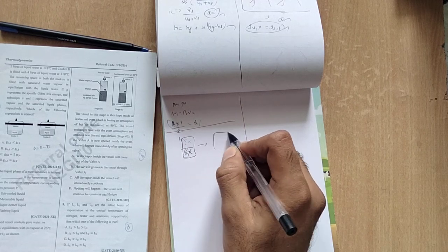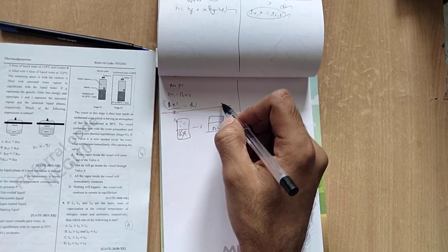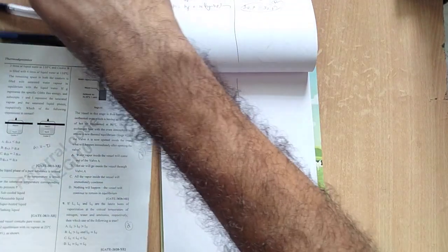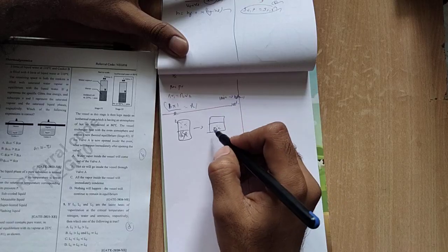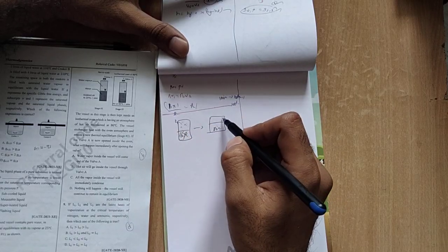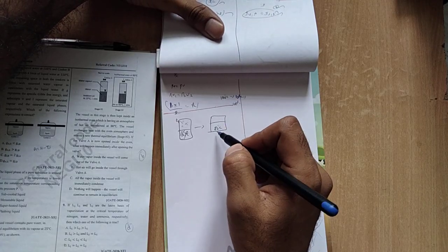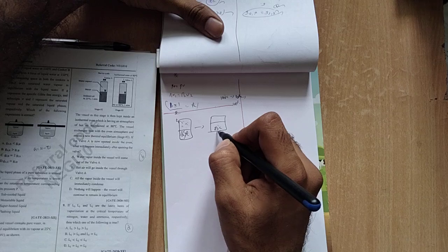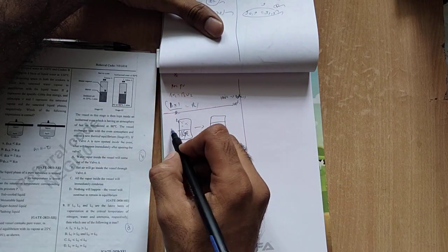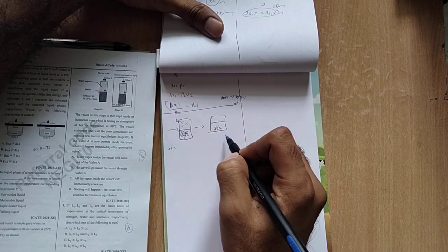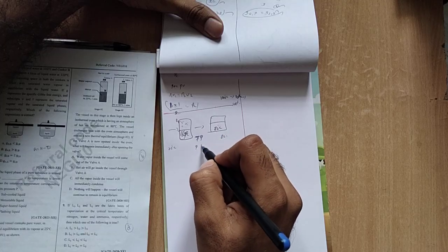Now we place it into 80 degrees Celsius. At 100 degrees Celsius and 1 atm it would become saturated. Since it is sealed, to attain saturation the pressure would be lesser inside. You got the point? Here it is only 80 degrees Celsius. Since it is completely sealed, the pressure inside has not been given. The ambient was 25 degrees Celsius, here the ambient is 80 degrees Celsius, so the temperature increases and the pressure also definitely increases.